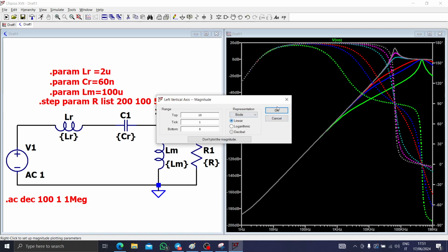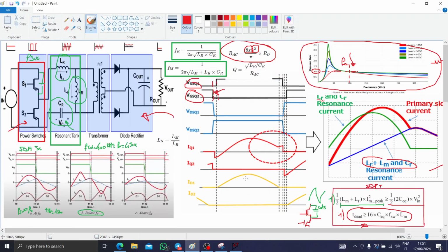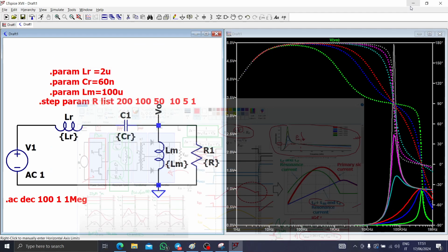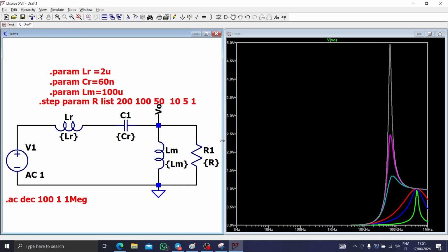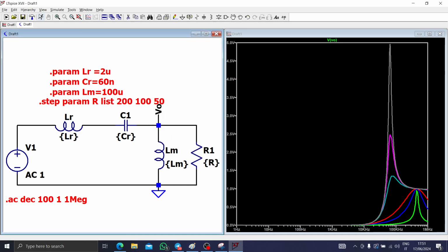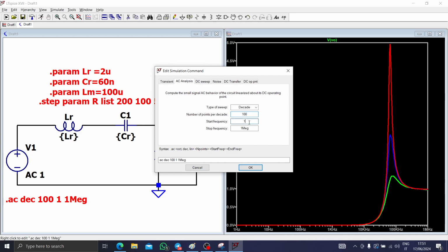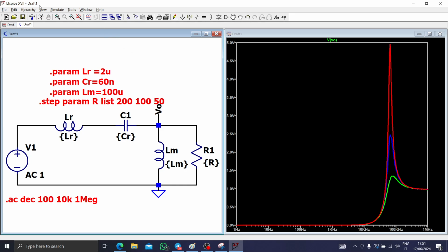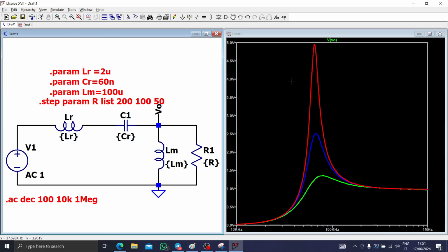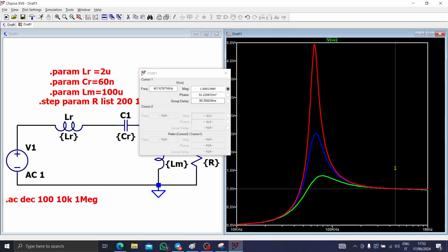Okay, but anyway, you have to put on linear, and you will obtain a graph very similar to this one here. Let's exclude the phase. We don't care about the phase. Actually, you have to put a lighter load like this. Okay, this is fine. And let's correct the zoom extent so you don't care about low frequency. Let's put 10K. And there you have it. So you have to search for the point in which you have 1 volt, and you have to block it with F4.